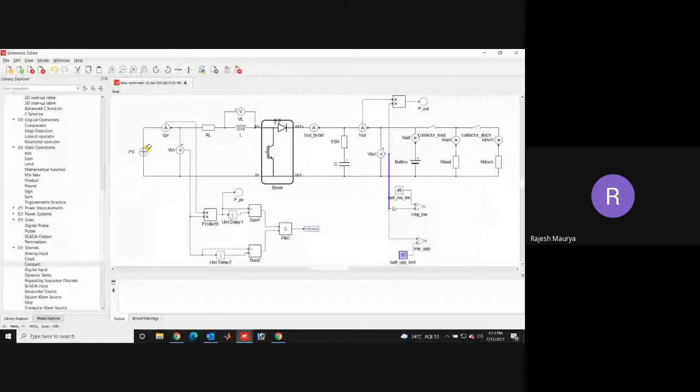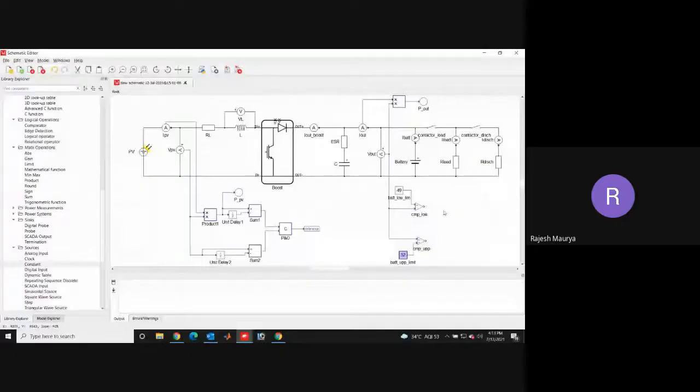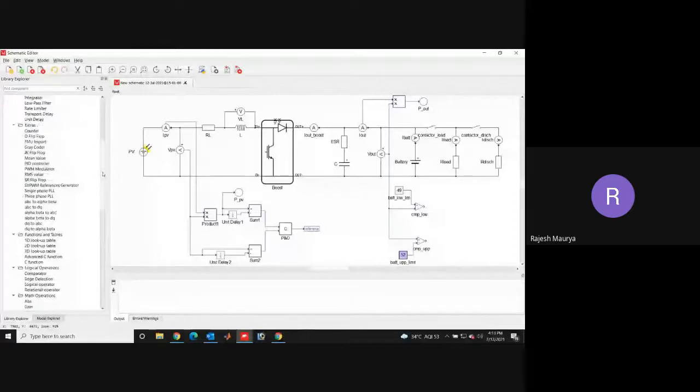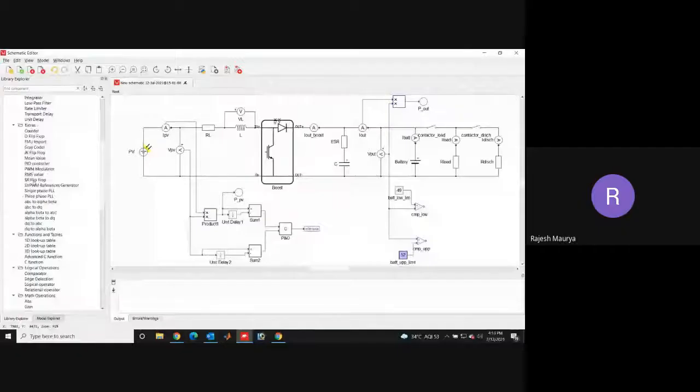That's the property. Now I take Alt. So where will I get this flip flop? In extras, you will find this SR flip flop. Okay, and I'll run. So from here I'll get the enable signal, and I'll double click on this SR flip flop and change the initial value as 1. So by default, it will be in on mode.